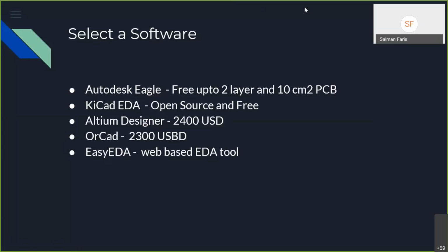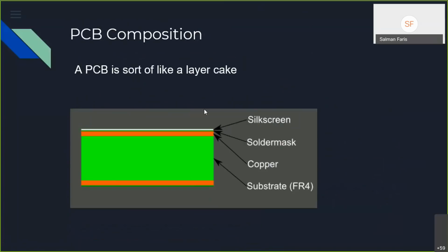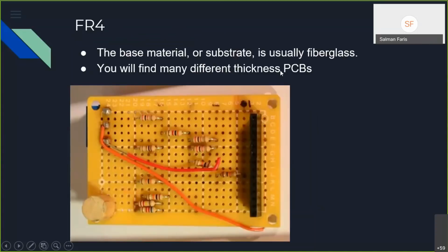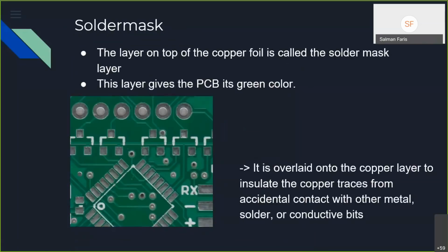I got another question. What does the number of layers in a PCB actually signify when I want to design a PCB? Actually, the number of layers means, you can see in here, we have a two layer PCB. That means this has one layer, and this has one layer, so we can also interconnect between them. How many copper sheets there are on the substrate equals how many layers we have. You need to consider that if you want to reduce the size of the PCB, you need more layers. Okay, so we'll learn more about it here.